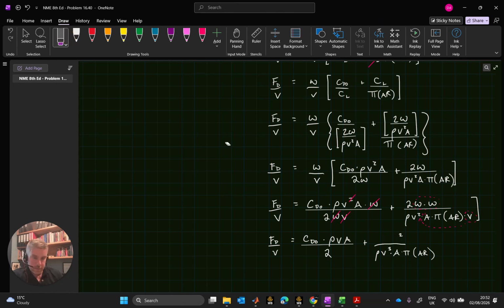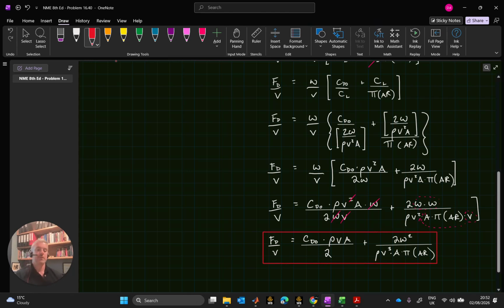Let's tidy up this second term here a wee bit more, see if I can centralize it, because I'm going to box this off now at this stage. I'll just keep it more presentable looking. All right, see if we can get that boxed off. Nice. So there's our expression. That expression there is the one that we're going to use. That's the general expression to give the optimal cruise velocity of a jet at some given elevation. Obviously, a jet of particular parameters flying in air of this density.